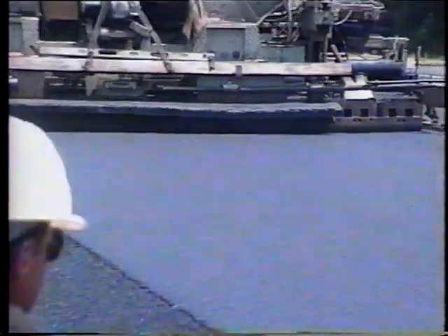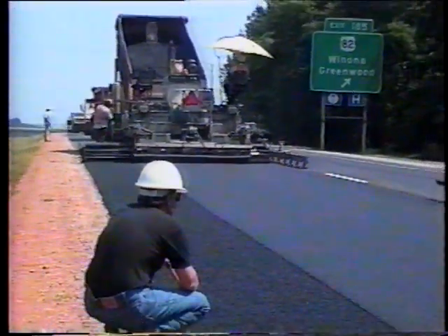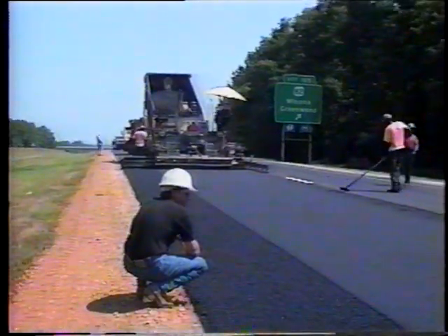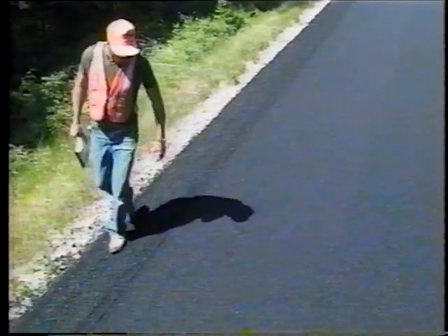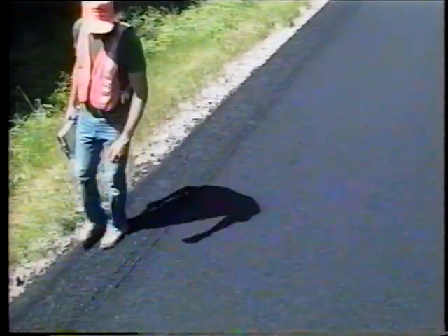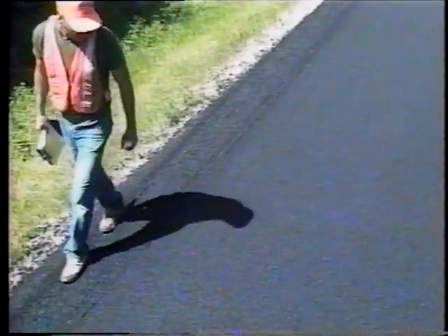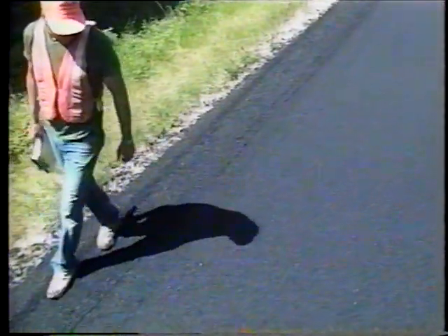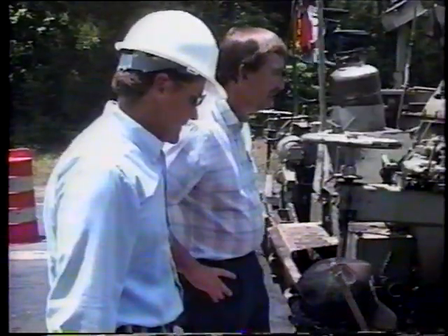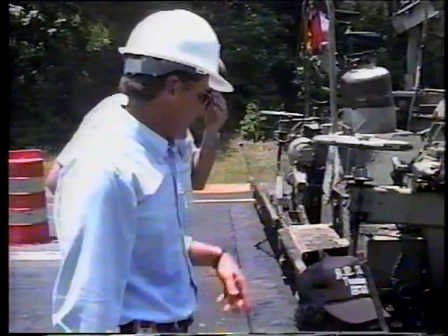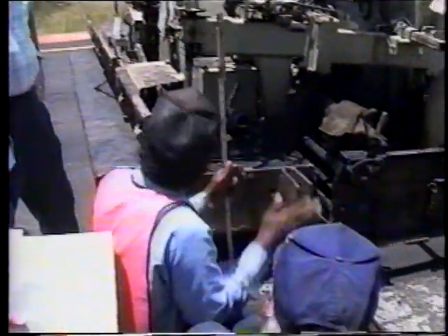Check the overall quality of the mat. It should be smooth, uniform, and free of blemishes. If it's not, something is wrong with the paver or the mix. And look closely again for segregation. If the texture of the mat isn't uniform, the mix has segregated. Inform your supervisor and the contractor right away. Again, we'll look at some examples of mat problems in Part 3. Keep in mind that very few operations will run perfectly, so the important thing is for you to communicate.